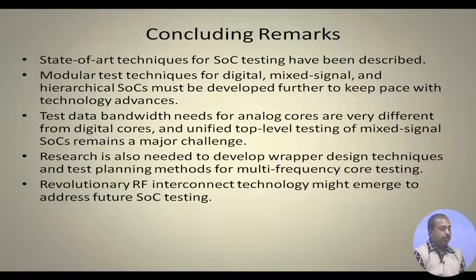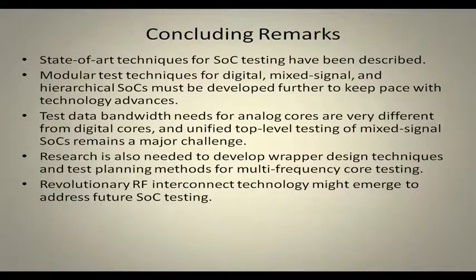Research is needed to develop wrapper design techniques and test planning methods for multi-frequency core testing. These wrappers are not capable of handling multiple frequencies, so maybe something can be done there. RF interconnect technologies are coming up. When the interconnects are operating in the gigahertz range, RF will come into picture, and it has to be taken care of.